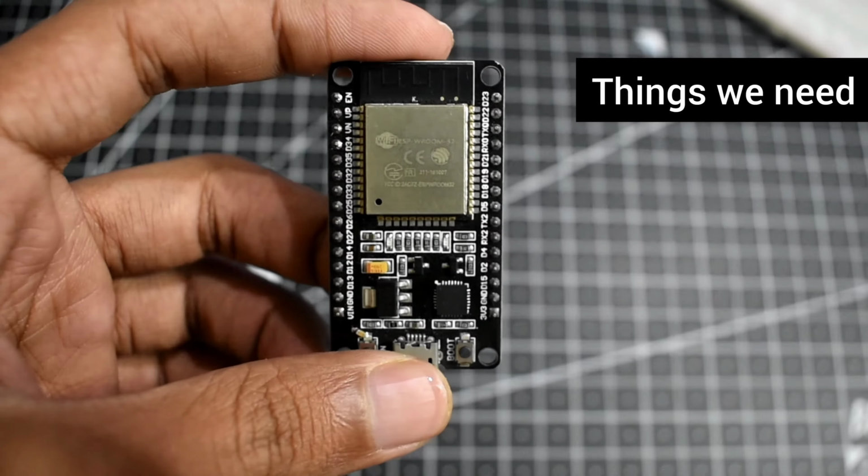Now in the void setup function, I need to begin with the DHT11 sensor. So I'm going to write here DHT sensor dot begin, because begin is the function or the keyword that is provided by Adafruit. Semicolon. Anything else that needs to be taken care of here? Not yet, not here, not here. And I think we are all done.